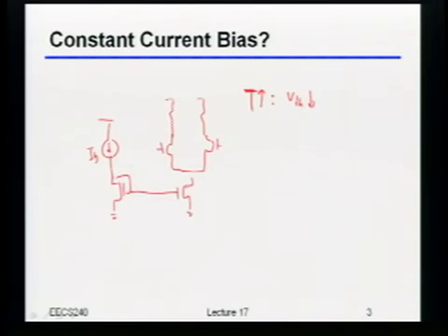Well, the bias current in the mirror would increase. Does it? Or actually, no, it doesn't. Okay, the bias current in the mirror stays constant, actually, right? So that's in fact the only thing that we've said is indeed constant in this circuit, so that we've kind of forced to be constant. What else would change? So gm, V star, gm, or whatever. Okay, gm. What's gm most likely going to do?